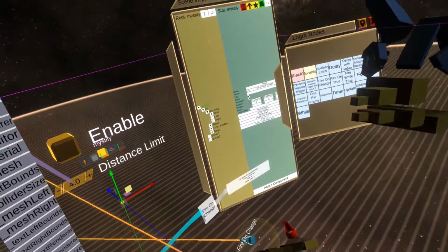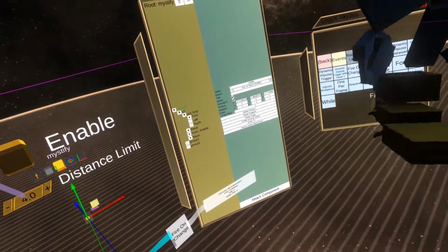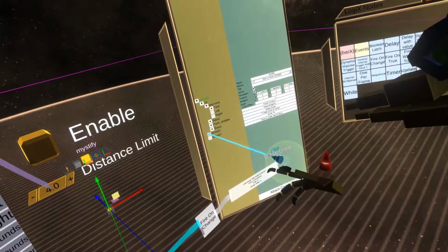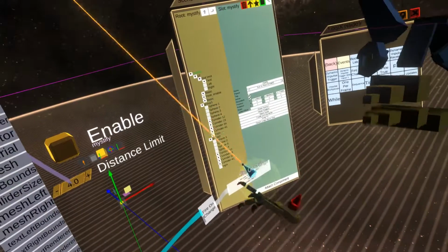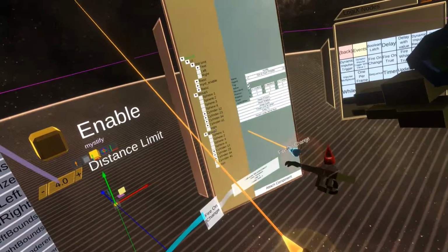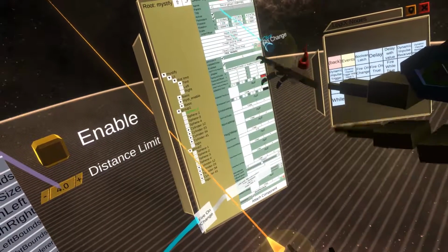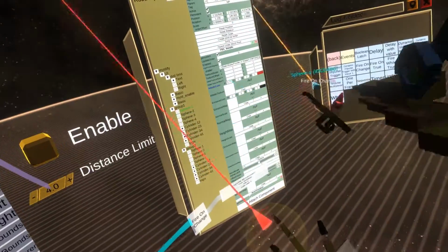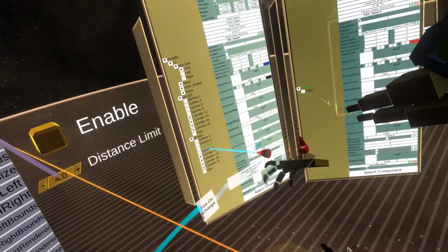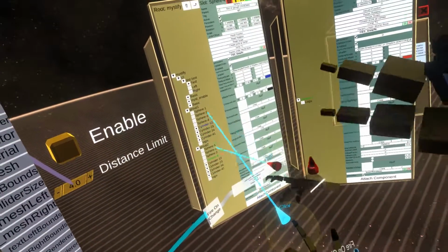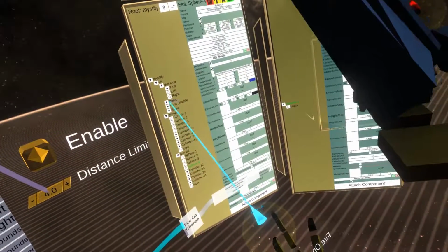Now, when that changes, we want to go through and change the positions of all those spheres that are at the corners, acting as the sort of control positions for this whole thing, which means we're going to want to loop through each group. Oh, you know what? I forgot to do one thing that I did when I recorded this video previously. In order to know which objects we're setting the position on, I'm going to assign a tag to these, and they are going to all have the same tag. Okay, all 8 of the spheres which form the corners of the lines now have the tag SPH, so we have something to look for when we loop through everything.